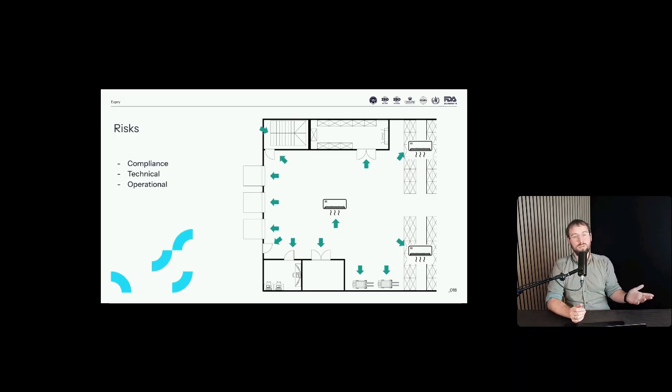You basically turn off your temperature control system and see what happens. How long does it take for temperatures to get non-conformant? And this should probably be done for winter mappings. It's just a matter of finding out how much time you have before you need to be back online. And door opening tests are basically where you define what you expect in terms of the number of door openings, not only doors, but also gates, unloadings, that you expect to have during a normal working day, for example. And then you simulate that.